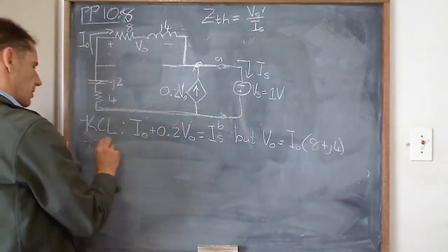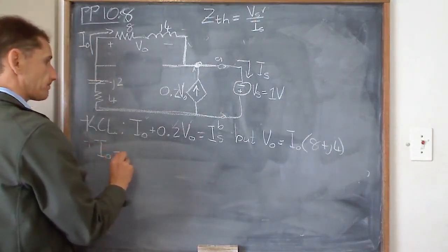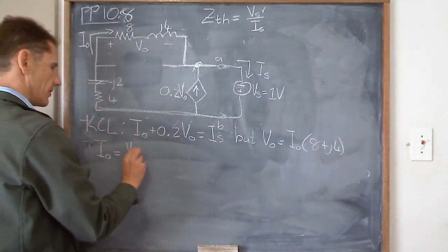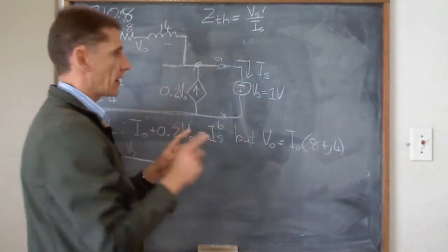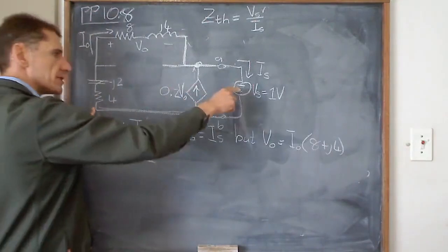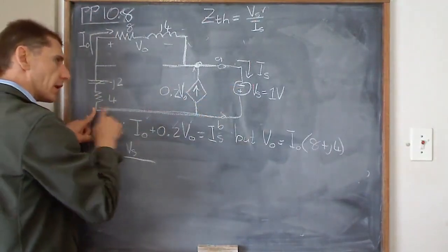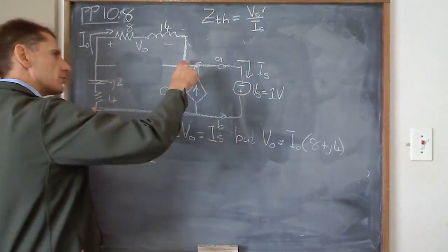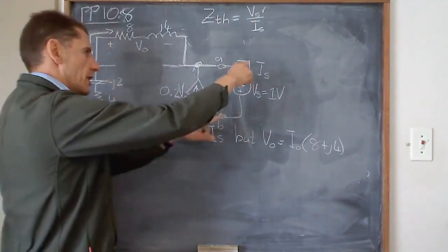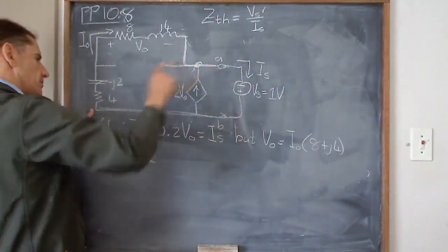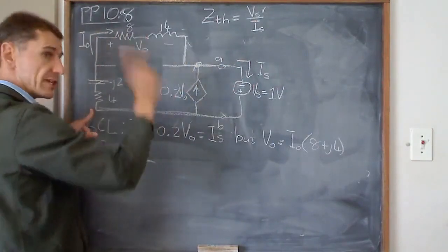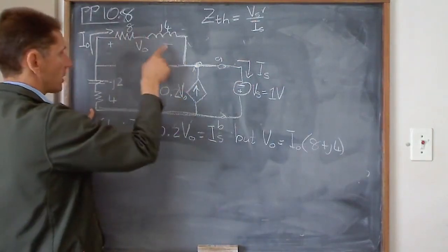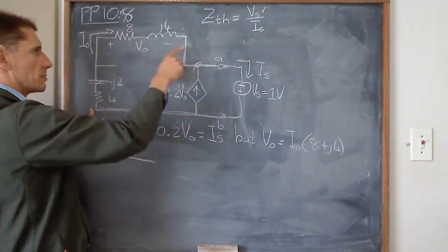Okay, so I out is Vs divided by this total impedance. And now note the polarity. I've got the positive at the bottom node, the negative at the top node. So this source connected across this impedance is going to push the current in that direction, which is what I want because I've got plus minus I out, and I've chosen this I out to be in that direction.